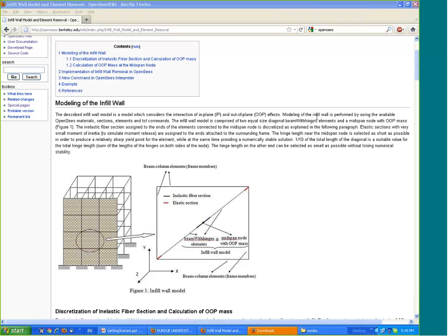From Olympia: does OpenSees calculate the ultimate curvature in a section analysis? No, it does not. Depending on how you create and define your material, you can make it fail at some point, but if you don't define anything, OpenSees won't do anything for you.